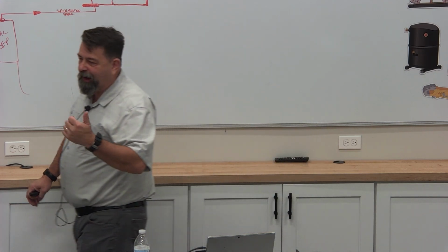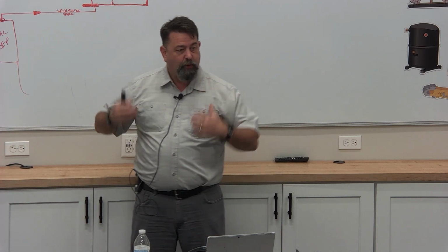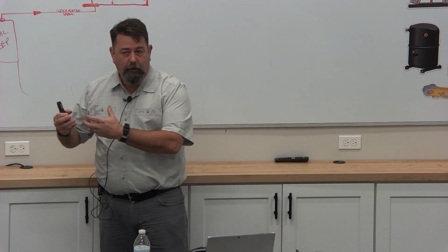Mandated. All right, so I don't know if you guys caught what he just said. He's talking about the entire system. Is it more efficient to have an HE case, a whole lineup of HE cases, a whole store full of HE cases? If I look at the power bill of this store, does the total power bill go down? Or do I lose that efficiency? I'm gonna tell you why: because I start compressors up, and I've got inrush current because I'm changing loads, because I'm running 6 defrosts a day or 12.